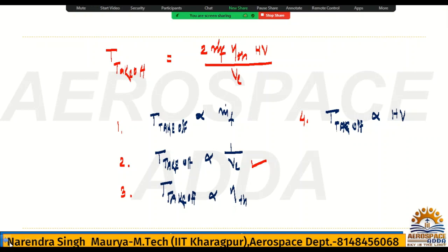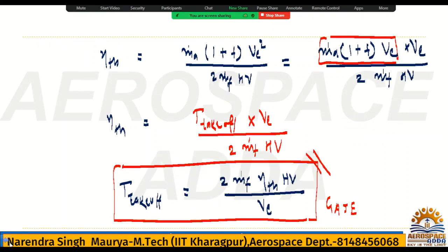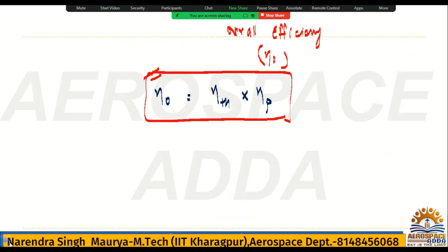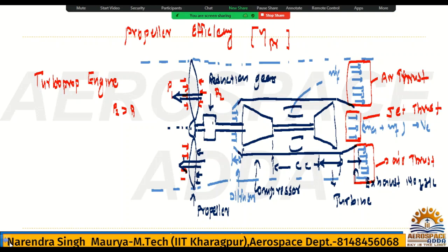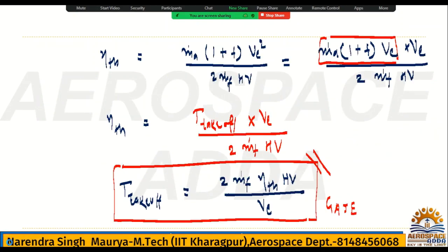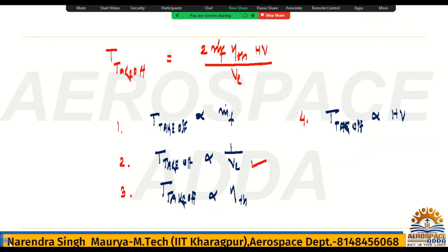So I explained just now, here the turboprop. Check this turboprop. The exhaust velocity here is less, so you are getting less thrust by jet only. Whatever thrust you are getting is because of the propeller. For that reason, the turboprop engine will have high takeoff thrust. That is the advantage of the turboprop actually. All right, fine. So this part is done.